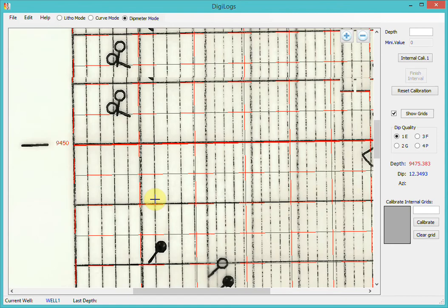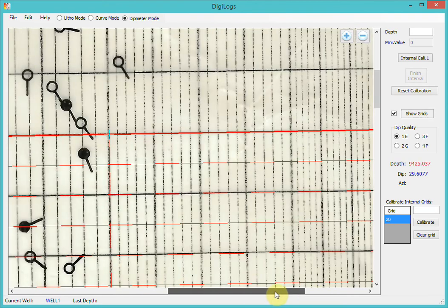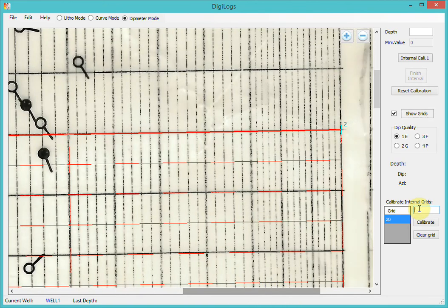As we can see, the default tangential scale doesn't match that type of scale. We can resolve this by defining internal grids. Here we can specify the limit of each group of scale. This is 20 degrees here and 60 degrees here.